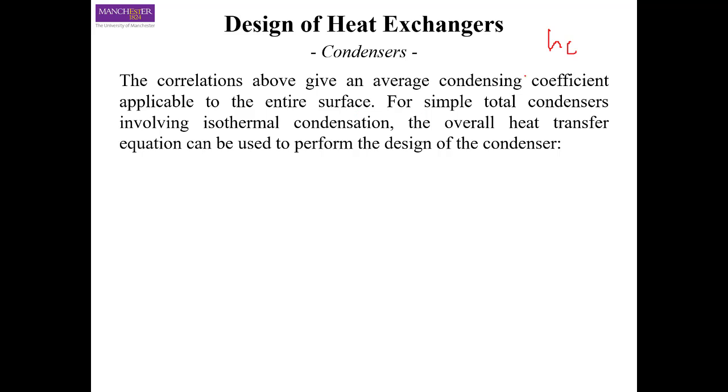Now, that value of Hc is actually important when we are looking at the design of condensers, because we need the value of Hc to calculate the overall heat transfer coefficient. And once we have the overall heat transfer coefficient, the rest of the design of a condenser is just like a routine heat exchanger like we did in lecture 7. So let's have a look at how we can use that for condensers as well.